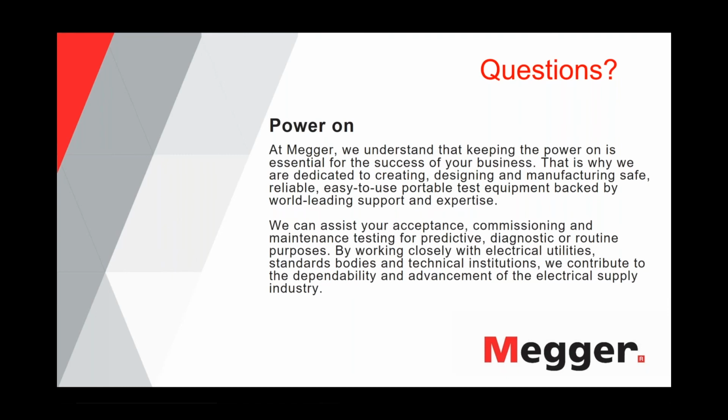known value for this, because otherwise I would put it right in the standard and tell you as an indicator, which would be great, but like I say, it's not possible, because we do not know what the aging characteristic is and how quickly aging advances in a cable, and it can be very different. You saw some three-phase cable diagrams, and many times one phase is different than the other two phases. Even if the cable was installed at the same time, one phase has a different tan delta than the other two phases. So there is not such a per year increase that can be used.